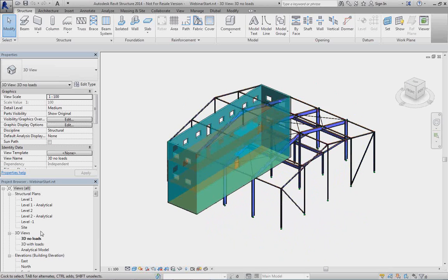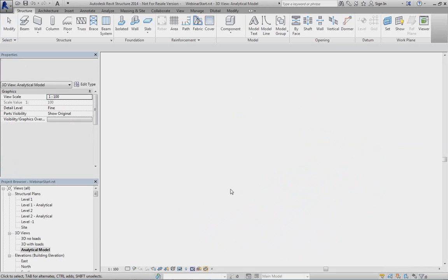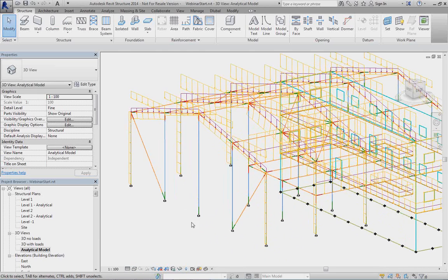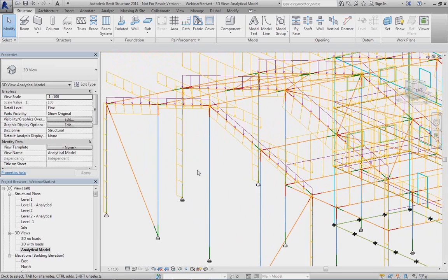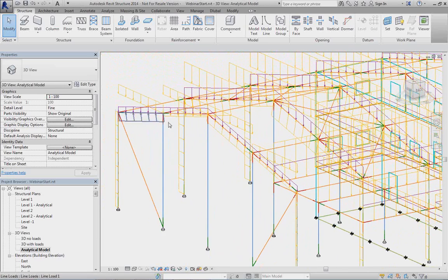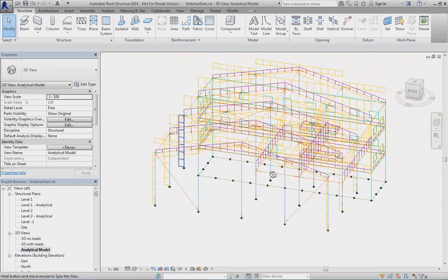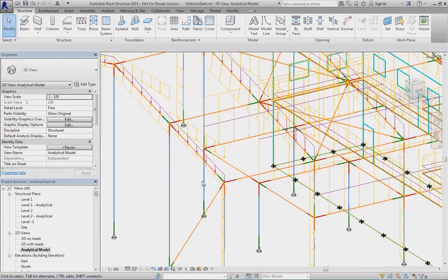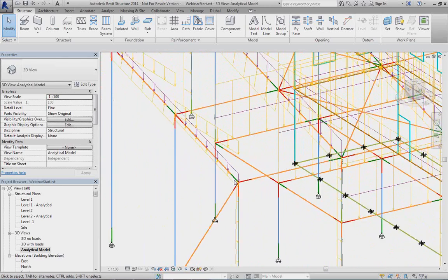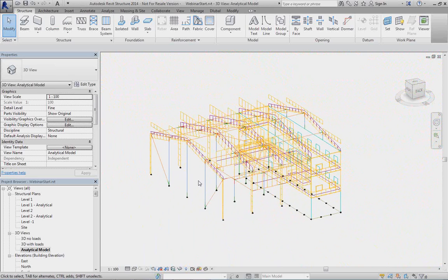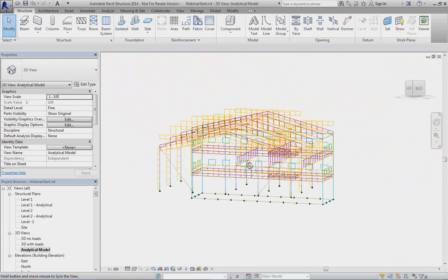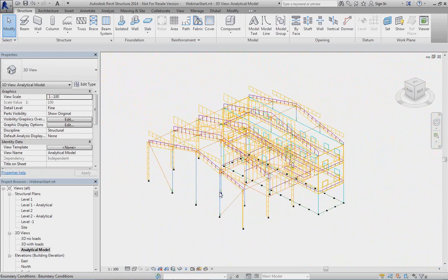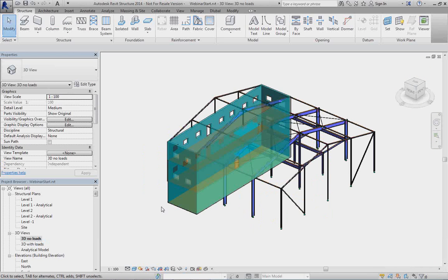This is now here fully modeled, including loads and load cases. We have here snow load, wind load, lateral load, support conditions. I took care of the correct alignment of the stick model in RFEM. The releases are set, and now we can use this model and we can export it.